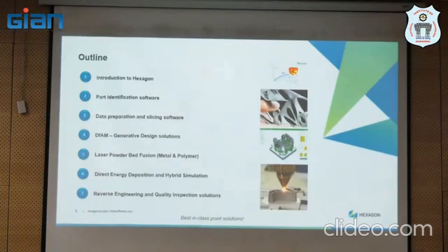So then, again, we are talking about a different set of manufacturing. 3D printing itself has 6 to 7 different technologies, like it can be FDM, DED or LPBF or other processes. We can check with the different set of processes. Then comes the quality inspection. If it is reverse engineering, I will start from here. So quality inspection either can be CMM or a regular 3D scanner.